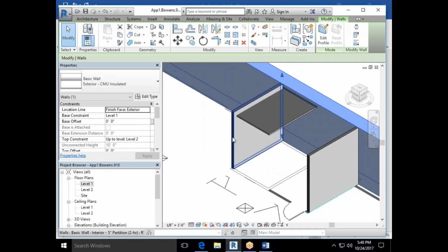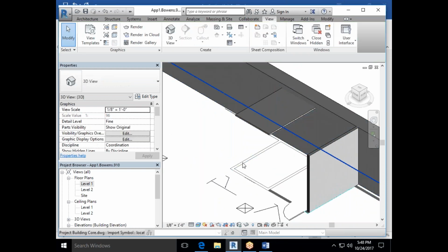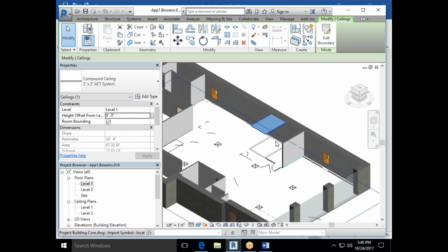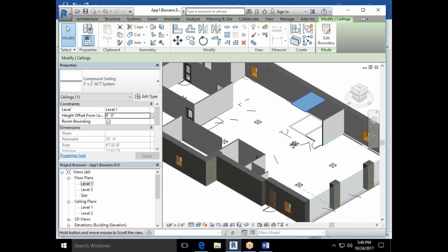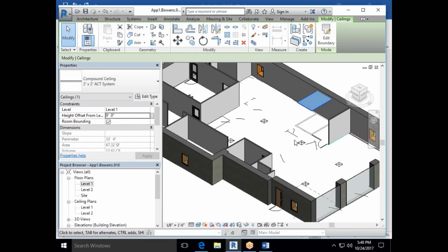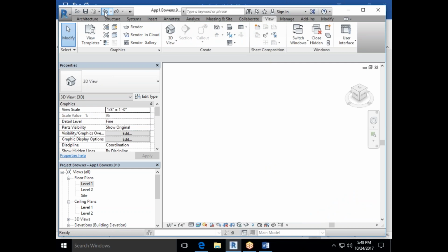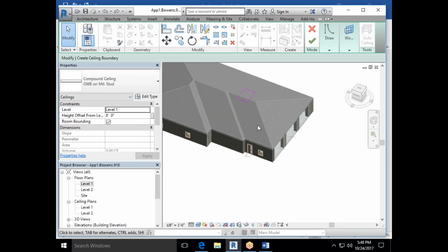It wasn't contingent upon its walls. So even if I keep deleting the walls, this is just like a floating plane in space that's editable. Editable by clicking it, highlighting it in my 3D view, typing in what I want it to be and changing its material. Not contingent upon the walls, which makes it a really free, easygoing process to add both the floor and the ceiling because they aren't going to give you a big warning message if something goes wrong. So let's go back because I've really cut this guy to shreds. I'll go back in time.